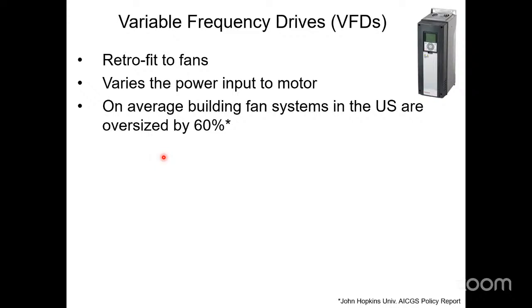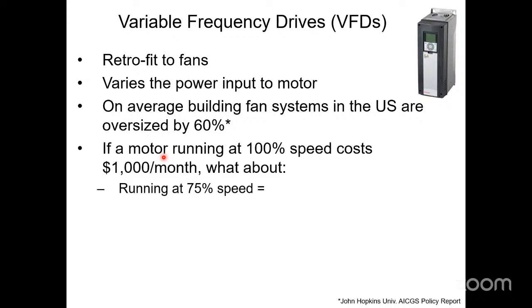If you ever see a VFD on a fan or a pump operating at 100%, I guarantee you that something is wrong with that VFD control. It should not be, or someone put it in manual and just cranked it to 100, right? It should never be at 100% because that means someone actually designed it perfectly and did not oversize the fan, which we know did not happen. So it should always be modulating something below 100%.